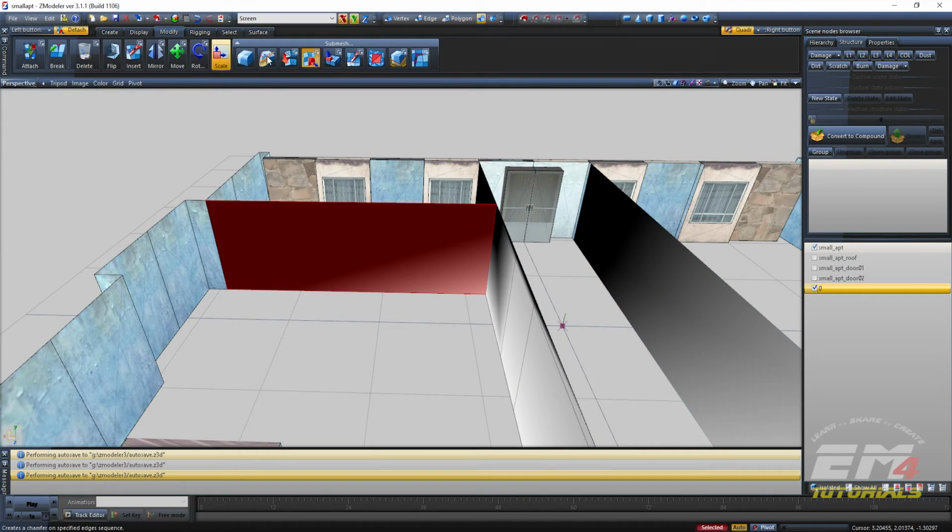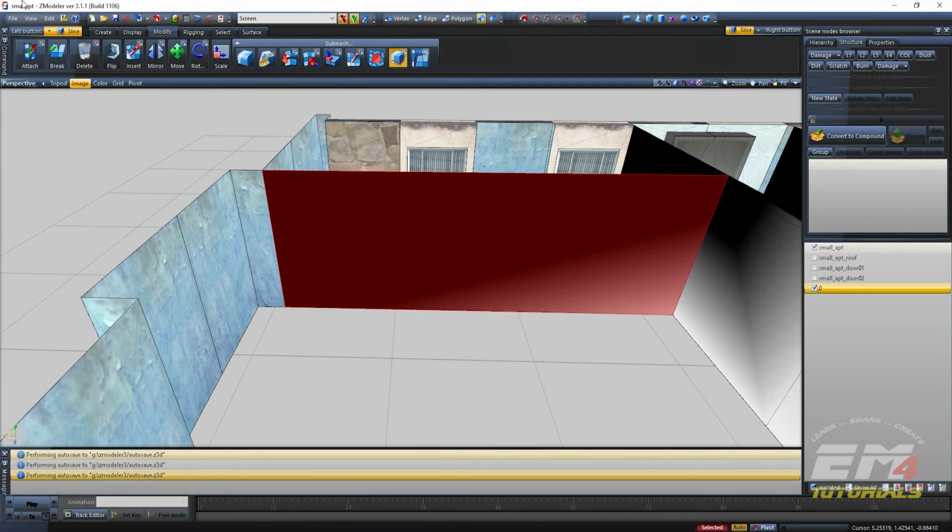And we are going to get our, let's see, our slicing tool. When you slice, it is very important that you take a very low angle, right? You don't want to be in a perspective mode and take the slice, because it's going to make the slice according to how everything is in your perspective. So that's the reason I went to a left perspective when I made the hallway, was so that the cut would be nice and straight. If I was to take a cut here, it would not be straight at all. So I'm going to take a front view in this case.